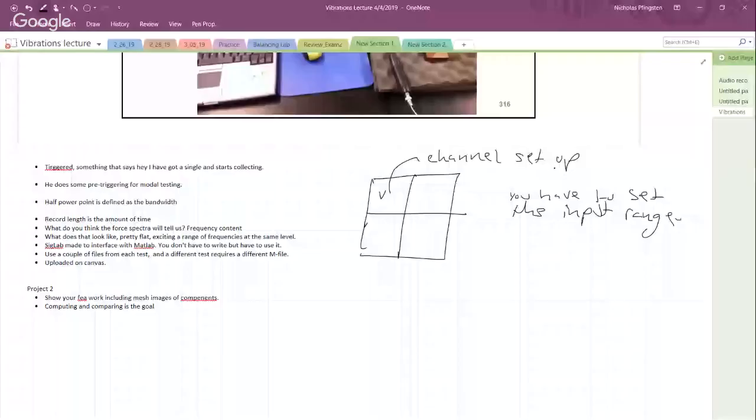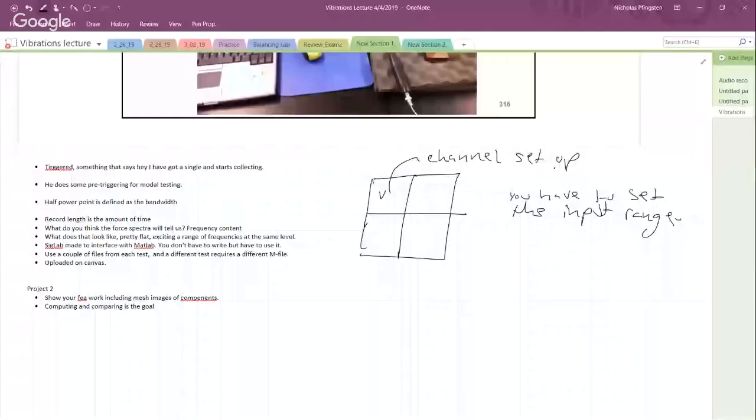right here for channel 2, the possible range is I could set it to auto, which is the thing I never like to do. People do that. 20 millivolts, 39 millivolts, 78 millivolts, all the way up to 10 volts. That's plus or minus. I had this test set to plus or minus 5 volts. That's my acceleration, the accelerometer. The accelerometer must be pretty sensitive. I'm not hitting these things very hard, and I could get a bigger signal with that range.